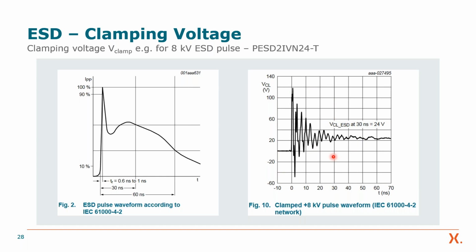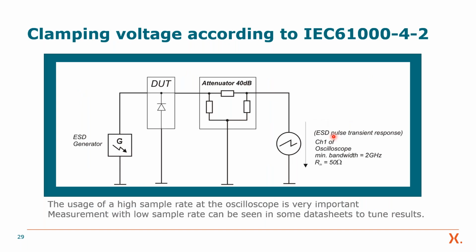So you can understand that, more or less, this is what the IC sees during an ESD event. Because most interfaces, especially in automotive and not that high speed interfaces like CAN bus and also USB 2 or something like this, are usually not that fragile when it comes to these very sharp peaks, this is why it's evaluated here after 30 nanoseconds.